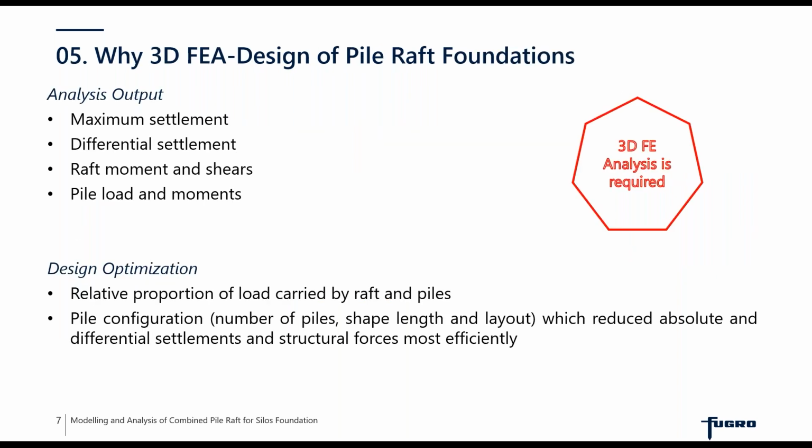Now, the question arises: why is a 3D finite element analysis required in the analysis and design of pile raft foundation? The first thing is the analysis output, which is required to understand the behavior of the superstructure-foundation system. For example, what is the maximum settlement? What is the differential settlement of the foundation? What are the structural forces in the raft and the pile after considering all the interactions? And this is possible only with the help of finite element analysis.